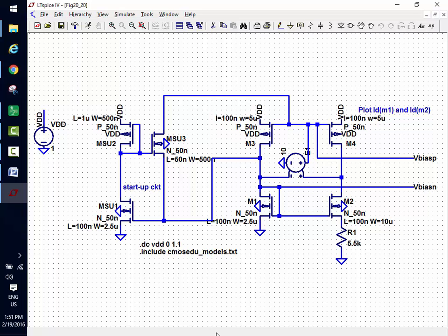what I'm doing. So I removed the gate drain connected device here, and then I'm going to put an amplifier in to try to hold these to the same value. And I want to re-sketch that and make sure everybody follows. Any questions? The drain to source voltages are independent of VDD. Remember before I had a gate drain connected device here? So as VDD went up, this voltage was VDD minus the source to gate voltage, changed linearly with VDD. So that causes the voltage across this device to change and thus the currents to change.